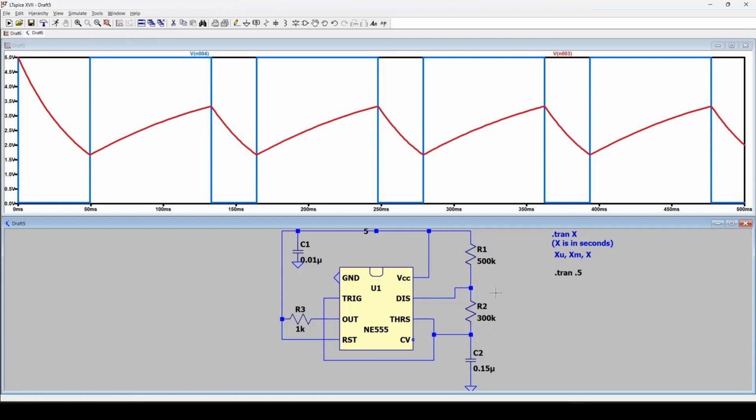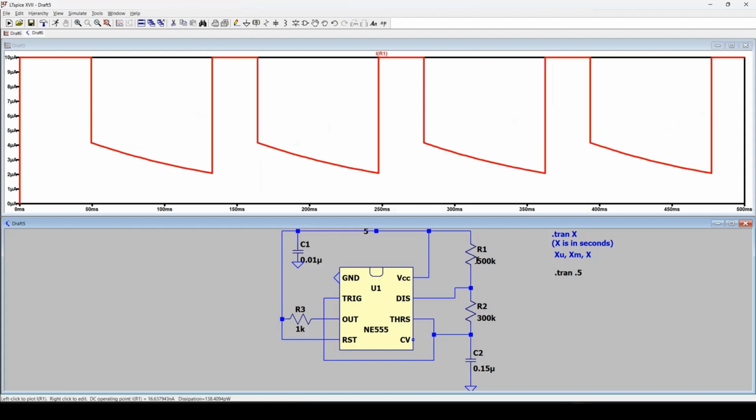So that's how you view voltages, but you can also view currents. So let's say you're hovering over a component. Now this time you hover over the component directly, not the node, the component directly until you see this black circle, usually with a red arrow, and that simply denotes current. So the black circle denotes current. And now we can see the current through the resistor.